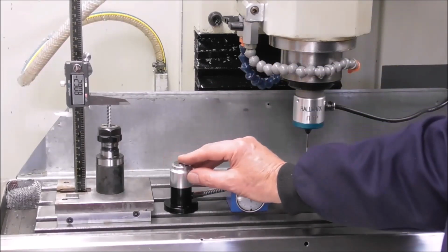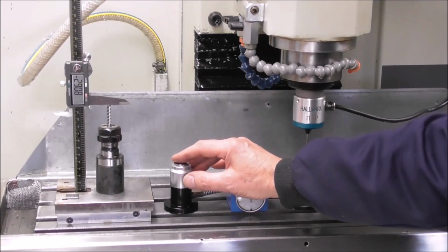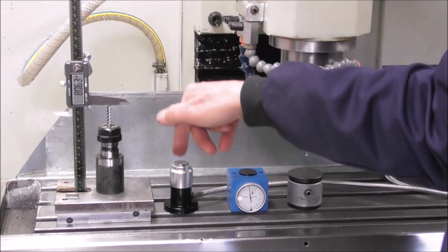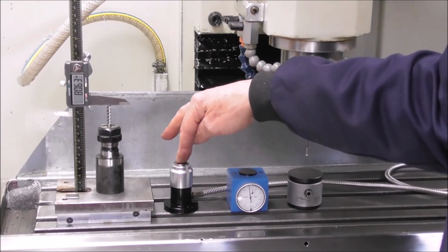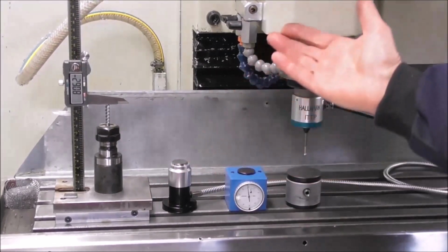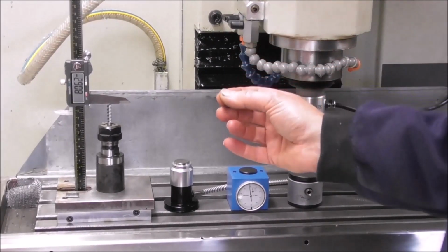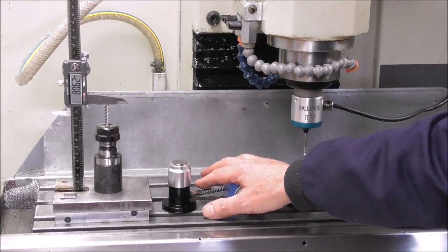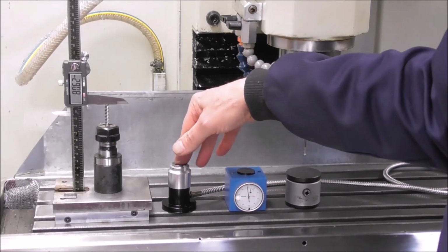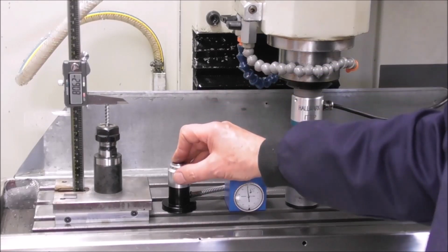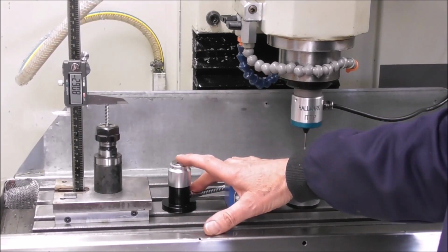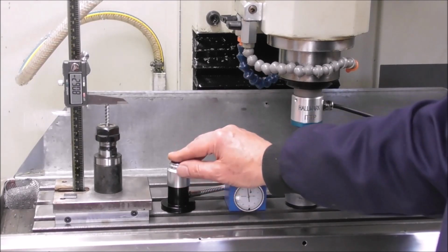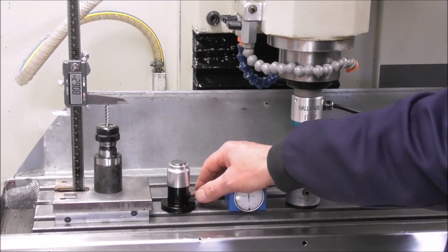But what if something goes wrong? Or what if you did something wrong? You forgot to plug something in or set something, or you've got a fault with the switch inside here, and so the head's coming down and it runs out of travel on your setter and keeps coming. You've got expensive spindle bearings and Z screw, ball screw and nut that could be easily damaged, not to mention your cutter broken and damaged and your tool setter broken. There's a lot of expensive stuff that can go wrong, not just the cost of the replacement parts, but the time involved in rebuilding your vertical screw and ball nut or spindle bearings. And so you want to think carefully, is that the right thing for you?